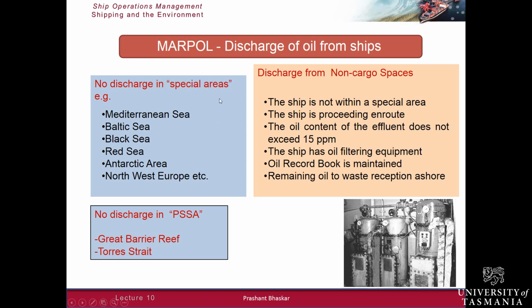And on the right hand side of the slide, you can see some of the requirements for discharge of oil from non-cargo spaces. That means from engine rooms. So it talks about things like, ships should be proceeding en route. There should be oil filtering equipment on board. There has to be an oil record book, and the content of the oil has to be a very small quantity in any mixture of oily water. So you can see from the slide, it's meant to be a maximum of 15 parts per million.